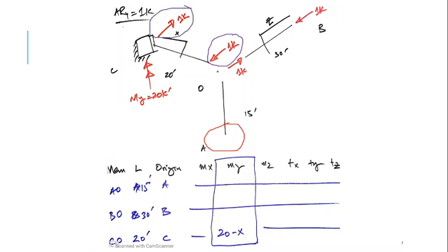It cannot be balanced here because it has no support. This load is in Z, this member is in Z, so there would be no moment here. This is in X, and if you move it towards this, it is forming a clockwise moment. So I have to apply an anti-clockwise moment.